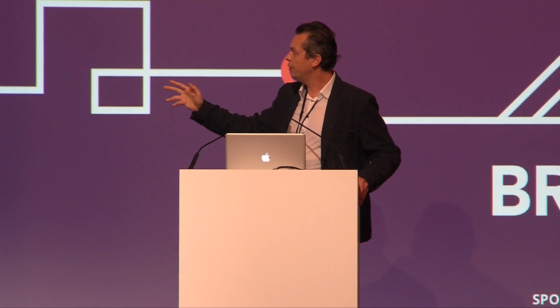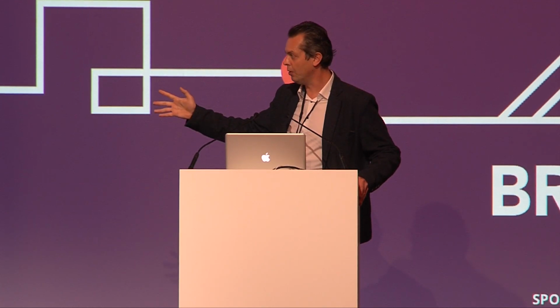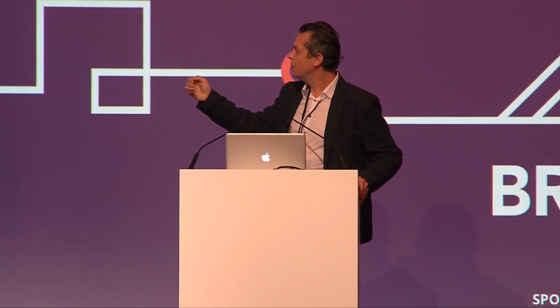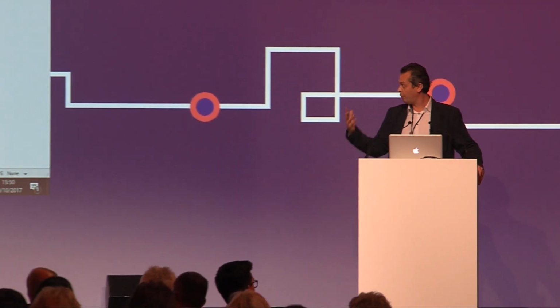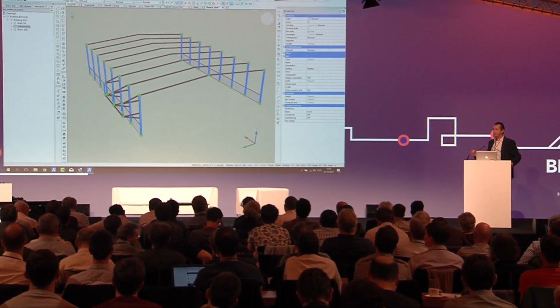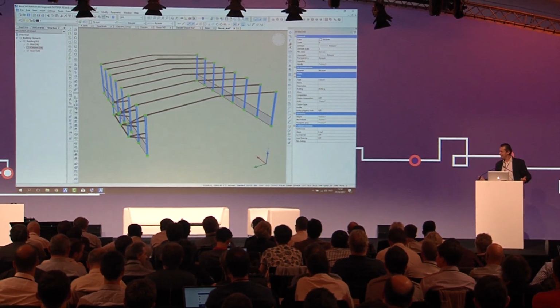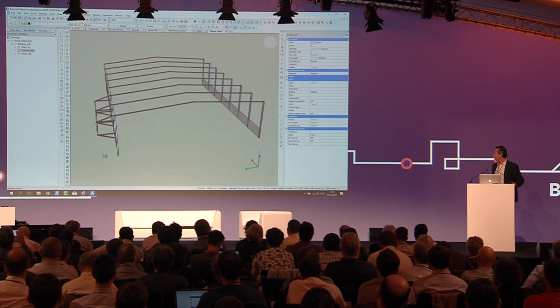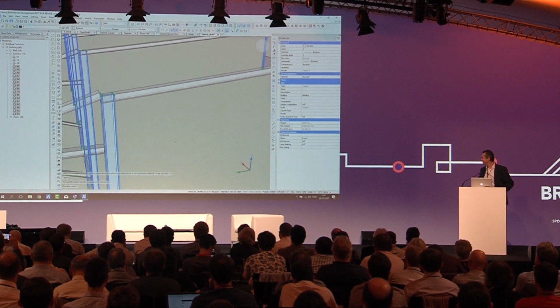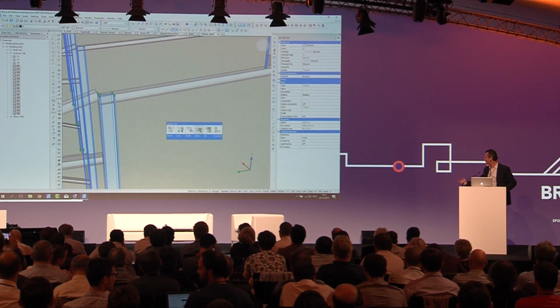And in the next step, we can first BIMify the model so that our BIM will recognize where the columns are in this model, where the beams are, what the walls are. So in this way, we already have a quick classification of where the structural elements are in the model. Now, in this case, we have no strength calculations, so for safety, we're going to increase the sizes of the columns and the beams, the sizes of the profiles.